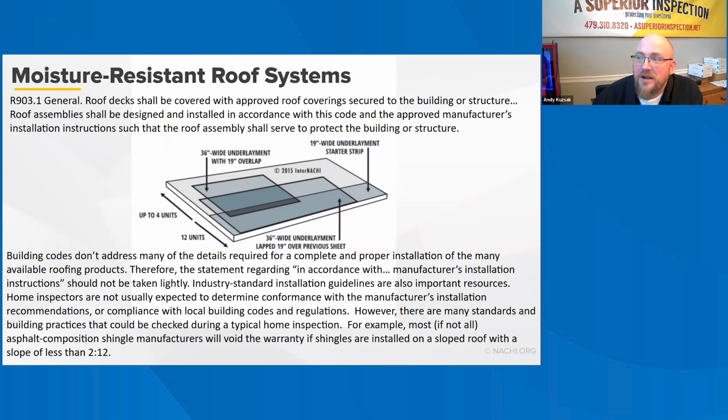Underlayment installations are not readily visible except for the possibility at the eave and rake by gently lifting up the edge of the shingle, but do not break the tack strip connection, and do not tear the shingles or damage the shingles in any way, if you're going to try and identify the configuration of the underlayment.